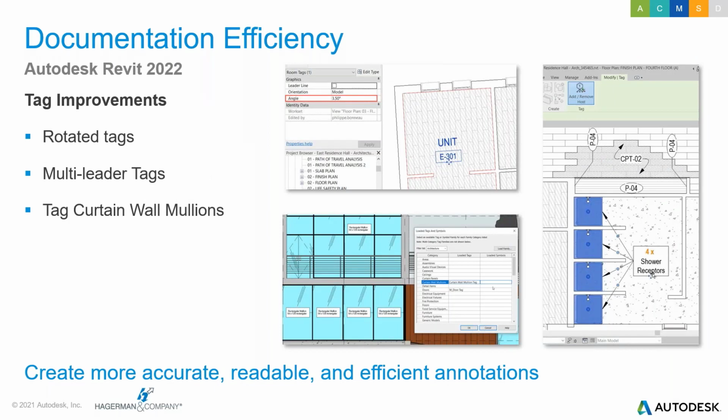All right, now here's a really nice one too. When you rotate a tag in Revit, you might like to control the angle very precisely. A new angle parameter for tags found in the Properties palette makes it easier to control the display angle of a rotated tag. If you rotate the tag with the rotate command, the angle value is automatically calculated, but you can enter a specific value afterwards if you'd like, or even before. This feature is easy to apply to tags in your views, giving you better control over your project documentation.